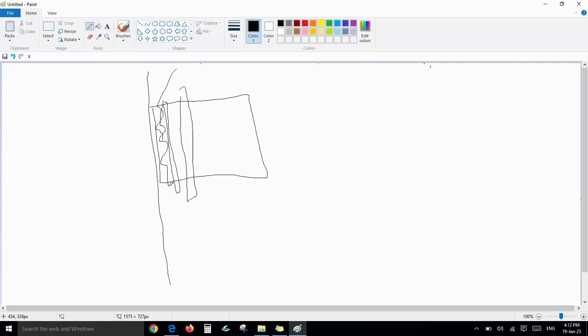So what we need to do is place a dummy cell which doesn't have a functionality. So end caps don't have any functionality. Even if it is damaged, I'll be very happy, as that won't create any damage to the functionality of the chip. Good.